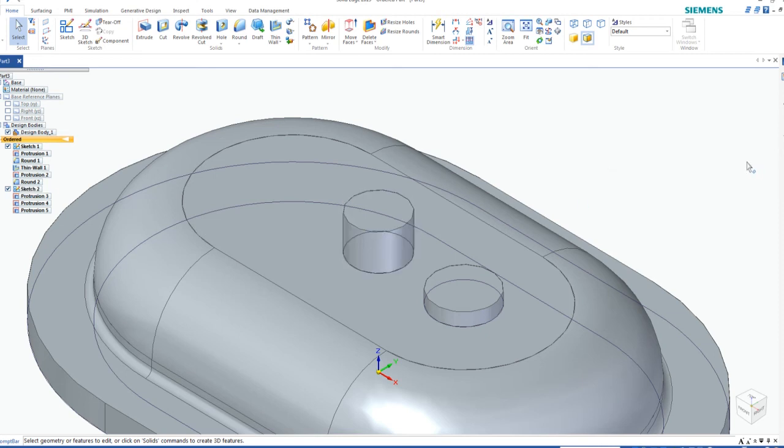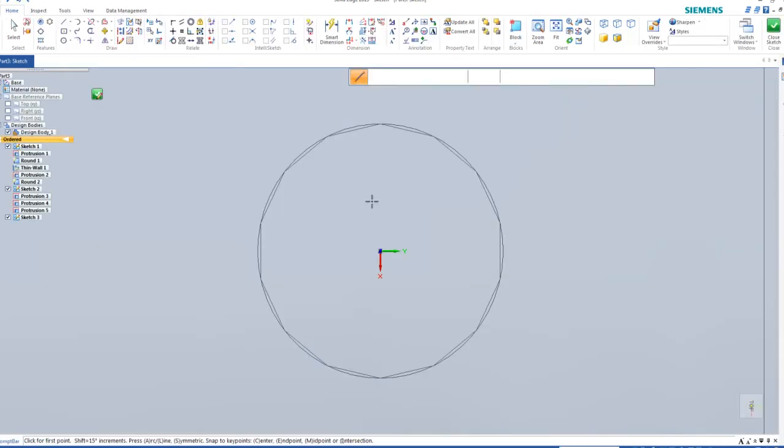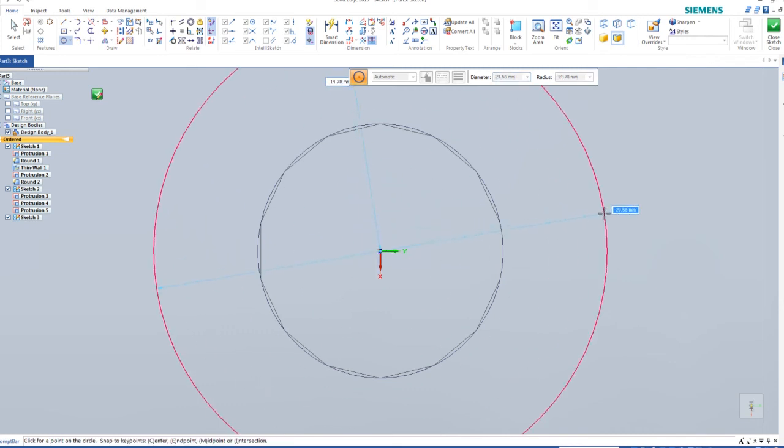We have a larger flange, which is a total of 30, and it extends upwards about 5. So we're going to add that one too. We're going to sketch again, select that top surface now, not this surface here. We're going to go back to our circle, find our center, which is right there, drag, and then just type in 30.